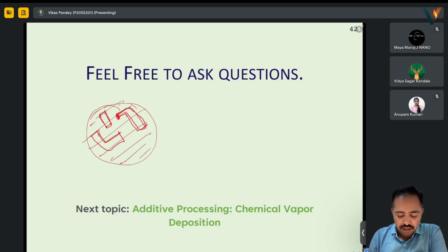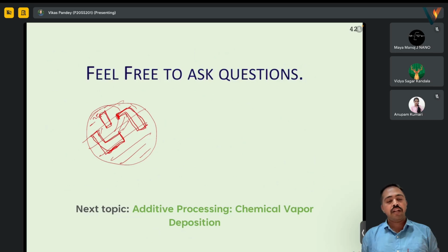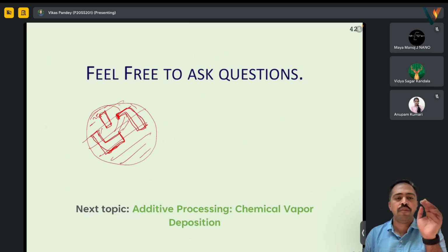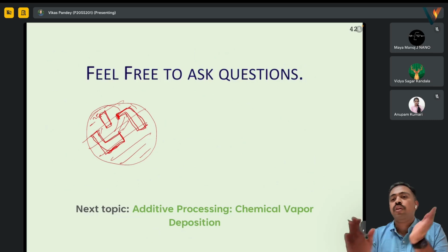You will learn about the lithography process and all. We will create something that will cover all other areas and keep just this area open, and then we will dip it into some etchant. Generally for this it is dilute HF, which will remove the oxide from that area.